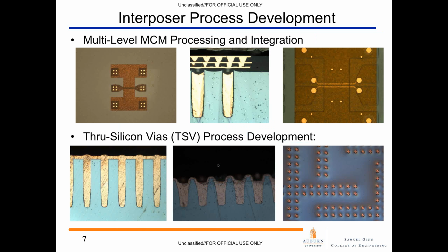To give you a little better idea what an interposer is: many times when they talk about interposers nowadays, they're talking about silicon interposers. An interposer will normally have thin film on top, which will have redistribution layers that take your fine pitch solder balls and redistribute them to the TSVs, and the through silicon vias are typically holes in the silicon that go all the way through and contact the other side. What I'm showing on the top left and right here are some of the upper metal of the thin film that's on the top surface and many times on the back surface of the interposer.